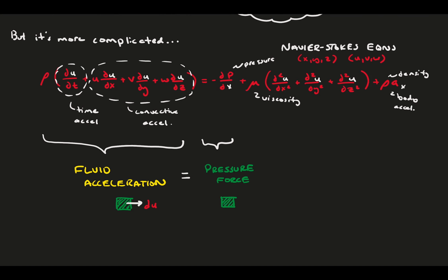First, pressure forces. A pressure gradient acting normal to the surface of a particle makes a force, and that force induces motion. Second, we have viscous forces. If the flow above you is moving a bit faster or slower than the flow below you, you feel a net force. These are primarily tangential, much like friction of sliding on solid surfaces.